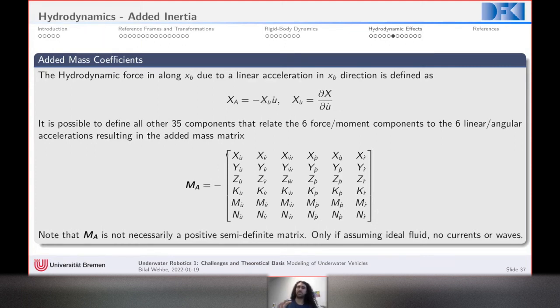So if we want to do a system identification, which is what you were just talking about, we need to start from a description of how much we understand the physics, put it in the water, run some experiments, collect data, and then try to fit or estimate these equations. We need to know what to measure, right? Exactly. So how many dimensions, etc.